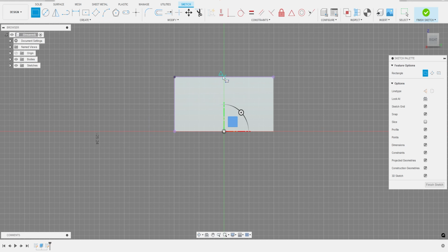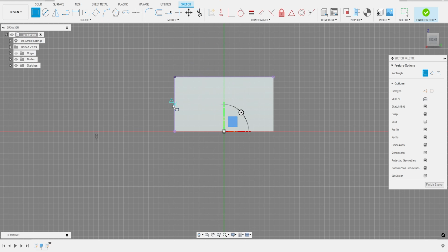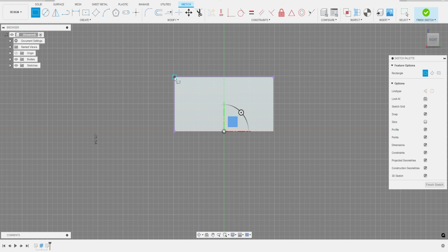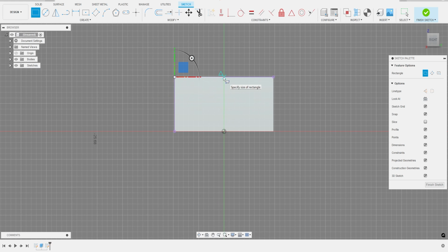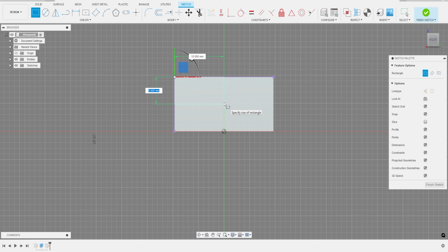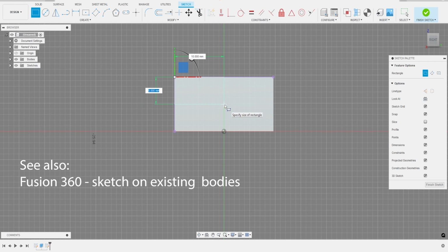Select a 2-point rectangle, move over the corner to snap on. You can see a square coming up, meaning Fusion sees this as a feature where it can snap on. Let's do that. Next, move over our projected lines. At some point, we will see a triangle, and that means we are exactly in the middle of our line. From the moment that was recognized, we can do the same on the other line. Just move over both lines until the middle has been recognized. It needs some practice, but now we can draw a rectangle that is half of our basic rectangle. Done. We can finish the sketch.